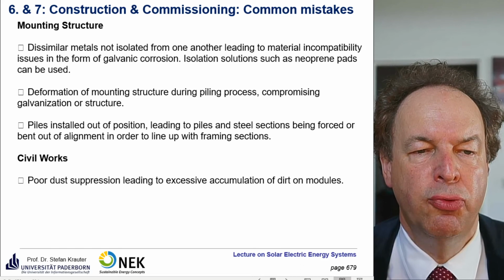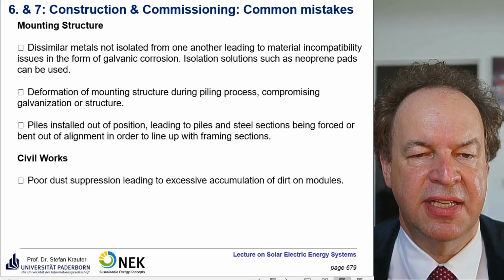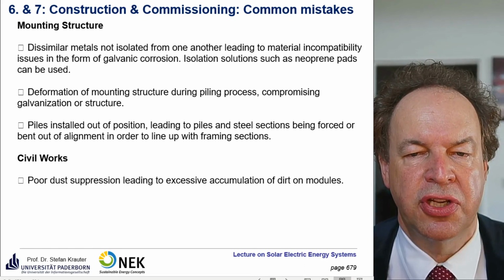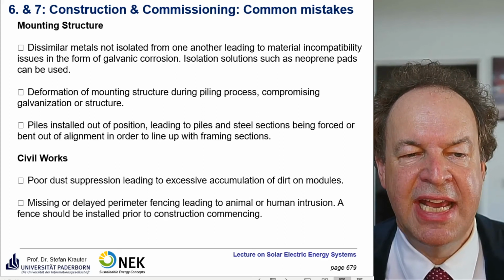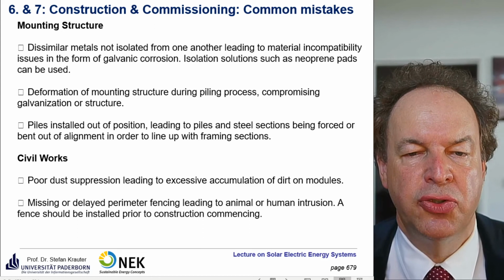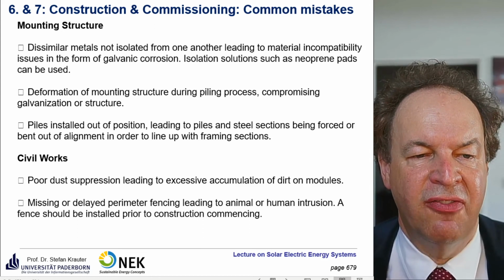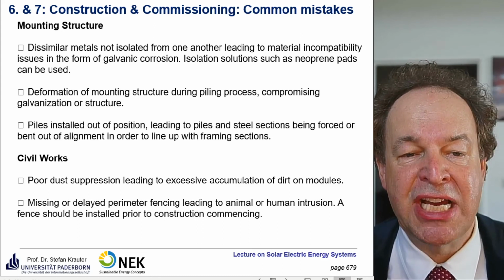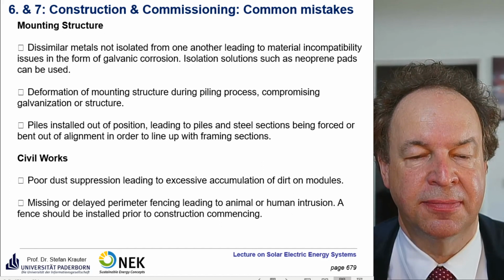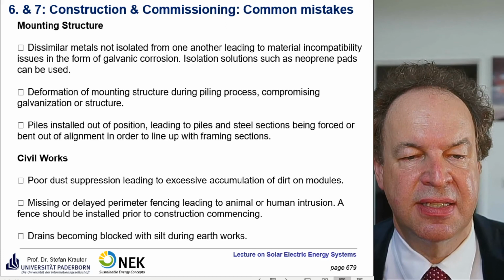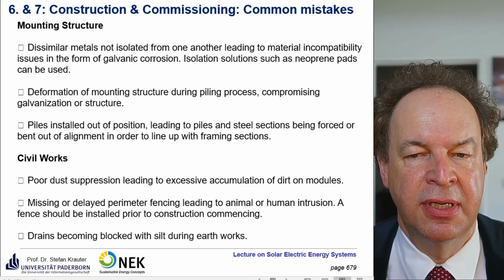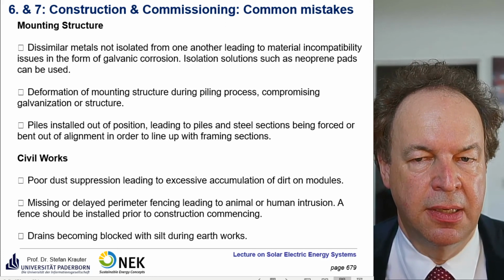Civil works: poor dust suppression leading to excessive accumulation of dirt on modules. Missing or delayed perimeter fencing leading to animal or human intrusion. A fence should be installed prior to construction commencing. Drains becoming blocked with silt during the earthworks. There could be some flooding then.